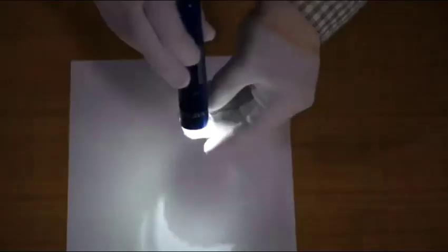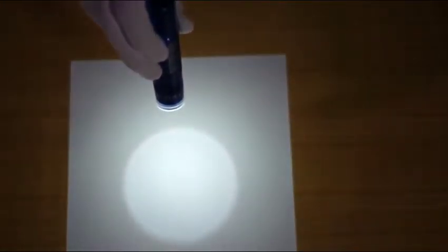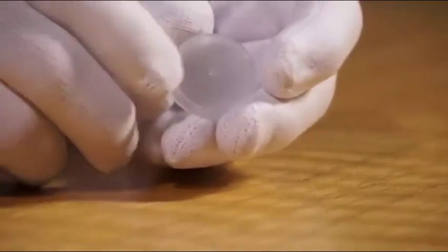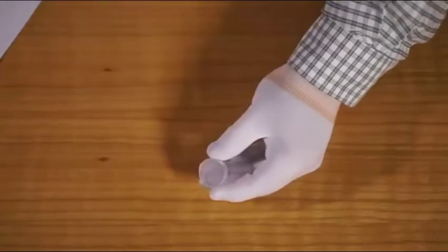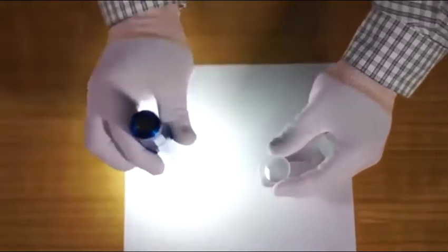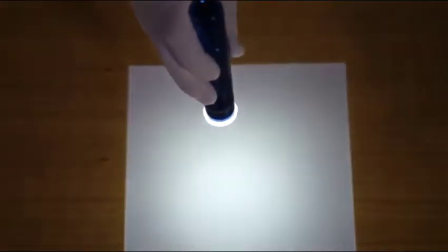One end cap included in this kit is highly polished. Any light transmission losses through this cover cap would be mainly due to surface reflections on each side of the cap. The mold for the next cap has been surface blasted with 3 mil glass beads. This process produces a matte surface that provides diffusion of the light with only a small amount of transmission loss.